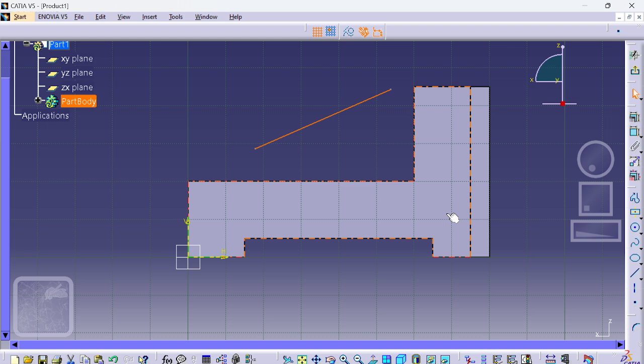ओके ओके. ये गड़बड़ है. ये वाला बंद करो तुम्हारा. ऊपर है देखो, 2 नंबर. हाँ, स्नैप पॉइंट चालू है. अब कंट्रोल जेड करके फिर से बनाओ, अब आ जाएगा. स्नैप पॉइंट का मतलब ये है कि जो ग्राफिकल स्क्वायर है, उसमें से ही काम करेगा, तिरछी होगी ही नहीं. हाँ, तो इधर लो. बस. ओके. हो गया.